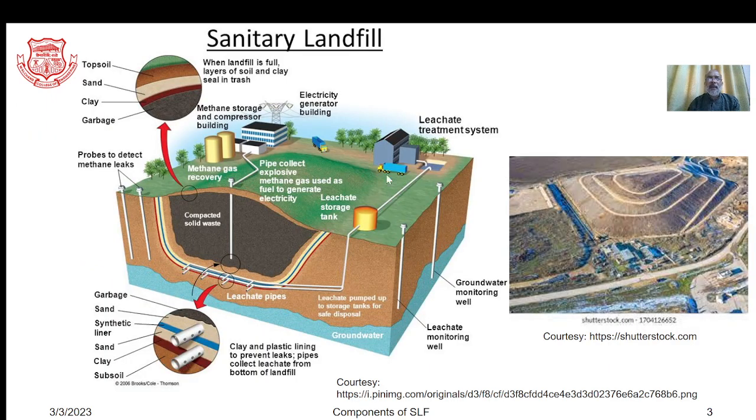So further, the structures are elaborated here. This is the compacted solid waste which is provided in the form of various layers. There is a leachate collection pipe. Further, it is provided with the various layers of sand, synthetic liner, clay as well as subsoil.